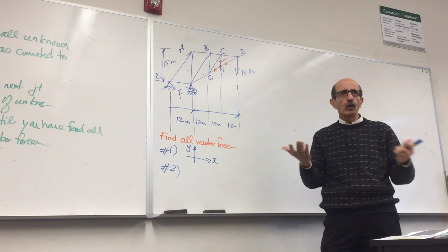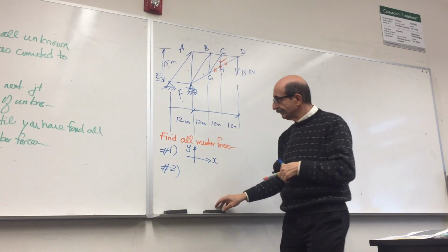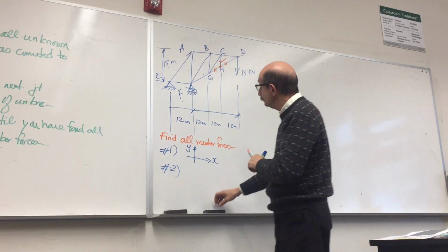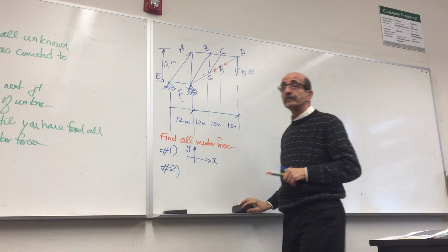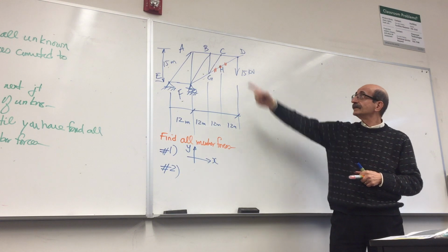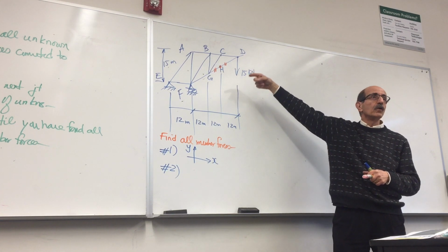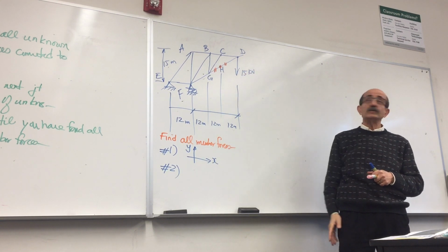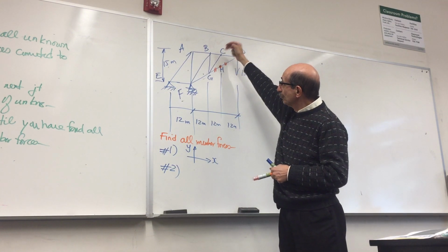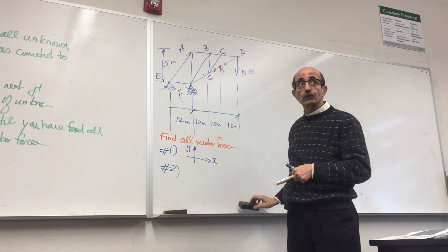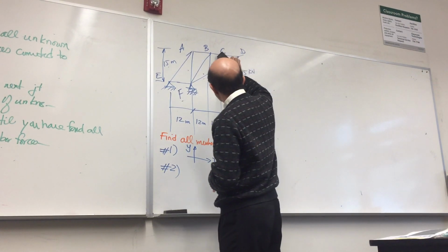Right? And you know what, right? I showed you basically. So this is gone. As soon as you remove that, you notice that C follows or satisfies the same conditions. No load acting externally at C, two of the members are collinear, therefore this is gonna go.